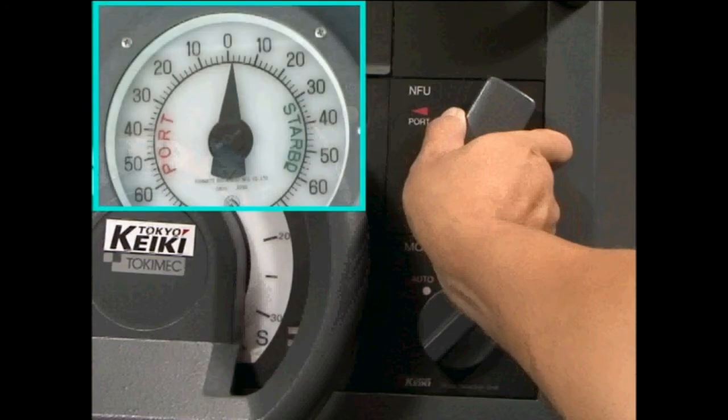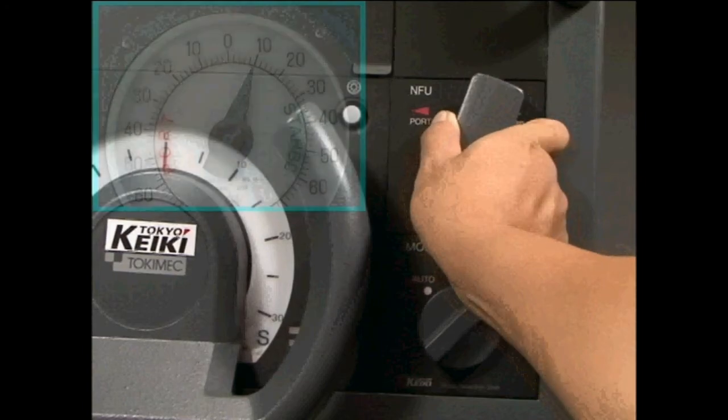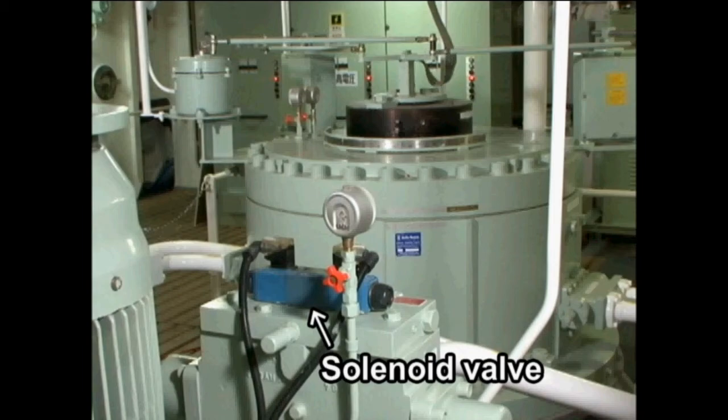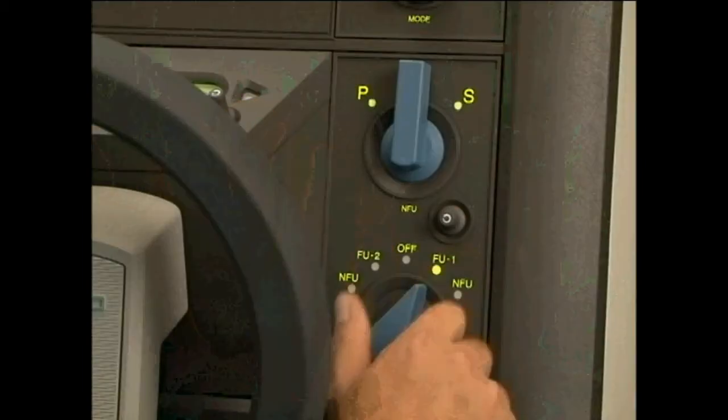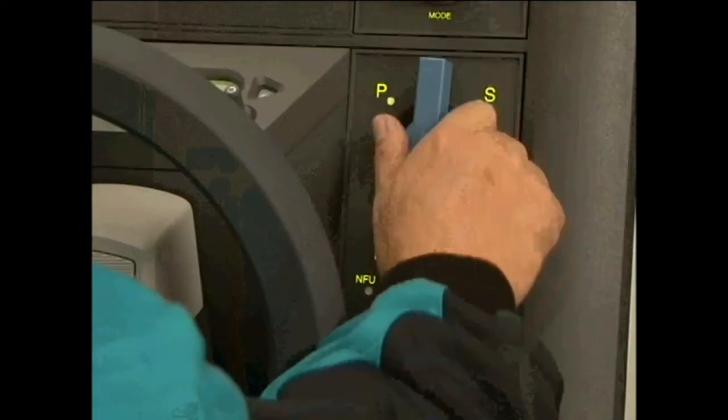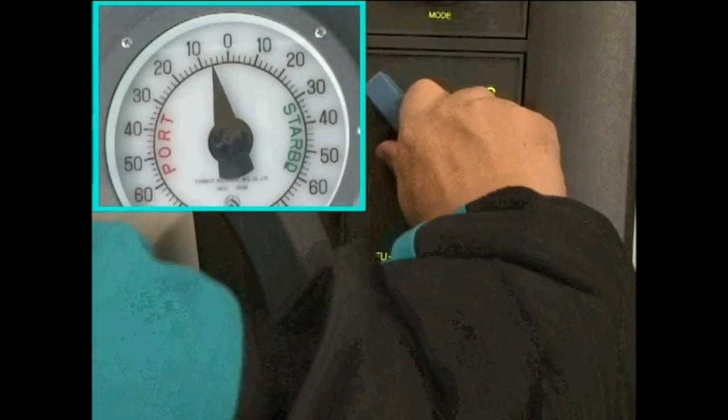Even if both the automatic and manual steering systems break down, rudder control is possible as long as the steering engine is operating. The steering engine's solenoid valves are operated directly and the rudder can be moved. When such steering failures occur, immediately set the mode switch to NFU and push the NFU lever down to the right or the left while looking at the rudder angle indicator.